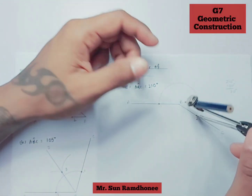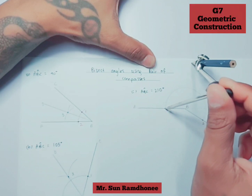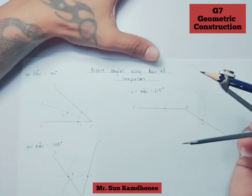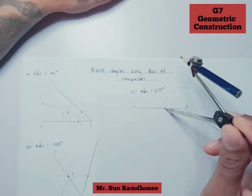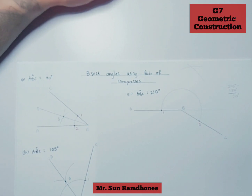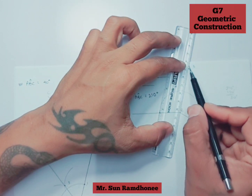So what I do is that I'm going to open my compass like this, and then I'm going to draw the arc. So the distance you open your compass will be approximately 6 centimeters, or you can measure less, but still you have to maintain the same distance when you're going to bisect. And this gives us point 3. We use our ruler and our pencil to draw line BD.